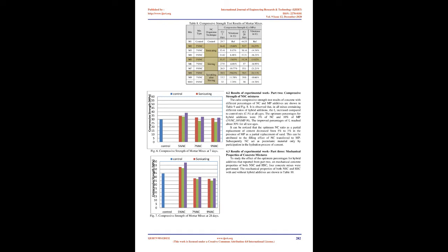3.3 Mortar mixing, casting, and curing procedures. SP was added to mixing water and blended until obtaining homogeneous solution. 70% of the solution was utilized to disperse NC. Sonicating process of this mix lasted for 10 minutes at 40 °C by water bath sonicator, while stirring process performed for 2 minutes by vane motor. Tables 3 and 4 show the specifications of sonicator and vane motor, respectively.